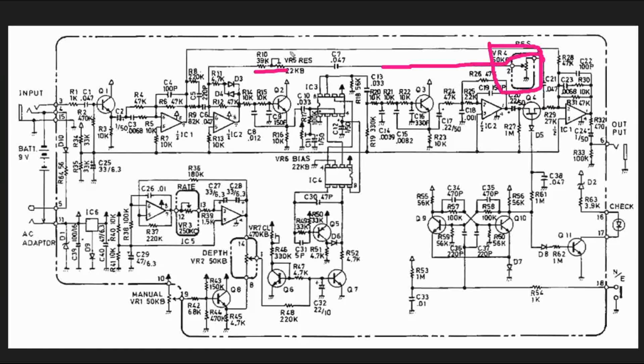And so this trim pot is an adjustment that gets made just to make sure that you don't get into runaway oscillations. Okay, you've got to limit the feedback so that you don't go off into really bad, crazy effects. With a PT2399, sometimes that oscillation can be kind of cool. In a flanger like this, it will pierce your eardrums and it is not pleasant. So that gets us through our whole signal path.